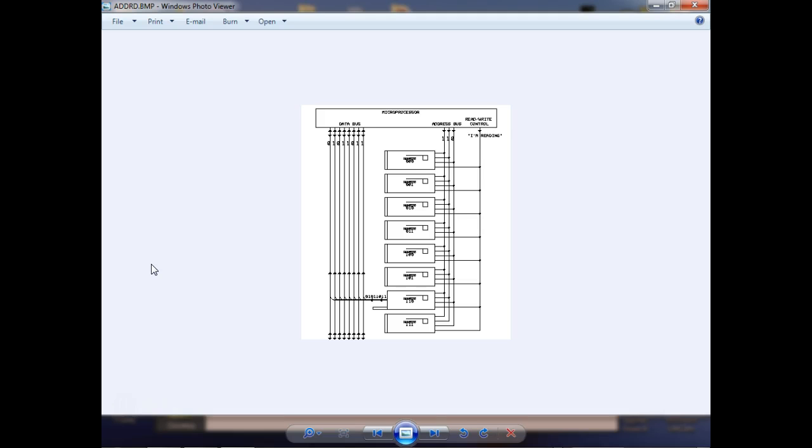I mean, memory buses are running up in the gigahertz now. Which is a billion, I'm not saying 1,000 million. So we do this extremely fast. And this is basically the way this works. So these addresses are binary addresses, by the way. With 3 address bits, I can only select 8 addresses. I'm not sure of the address bus size now. They're pretty big. I think it's around 64 bits or 64 different wires. And this is why when you actually look inside these things, you see a ton of stuff.